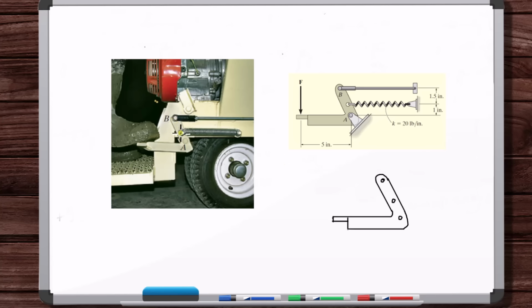statics and even dynamics is we draw these free body diagrams. We make sure that we draw them accurately. They have to be drawn correctly. That's so important. We have these correctly drawn free body diagrams, and there's known and unknown forces applied. And then from there, because we have some known forces, we can solve for all the unknown forces. So here, for example, the pin force is unknown. So we solve for the unknown pin force, and we can use that information to get the size of pin we need and the strength of pin we need.